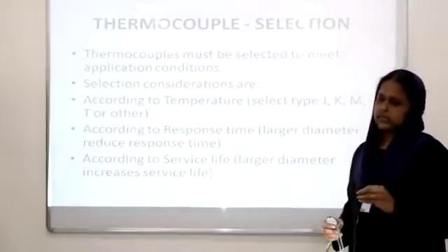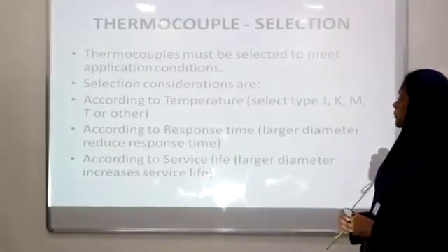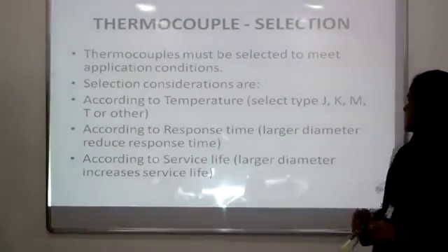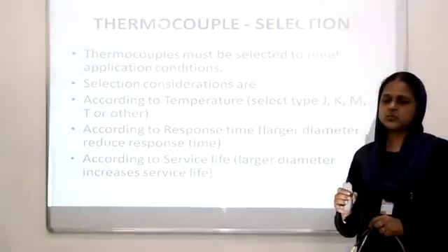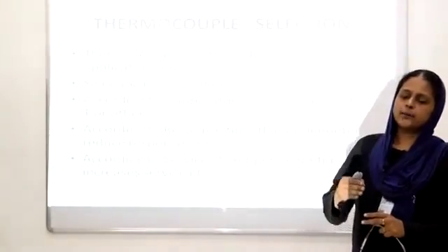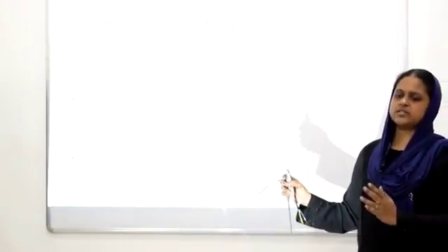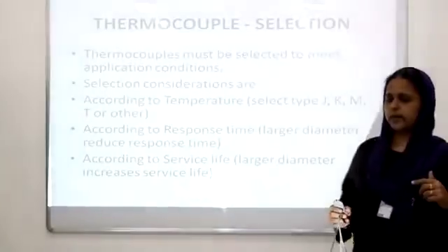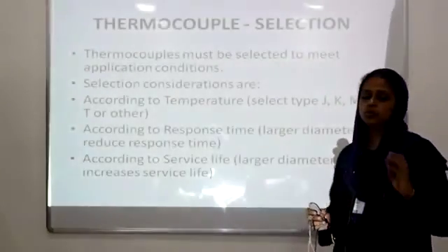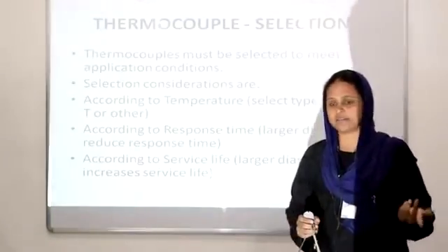Based on that, what characteristics should be considered before selecting thermocouples? A thermocouple must be selected to meet the application and conditions. If I want to use it for a particular process, I have to know the minimum and maximum range of temperature measurement, then only can I select which type of thermocouple to use. I have to know the application and process conditions; then only can I select the thermocouple.